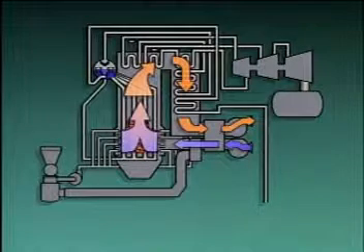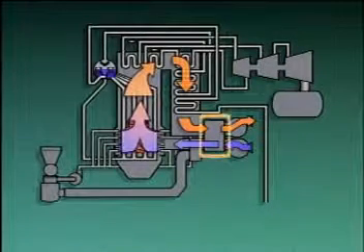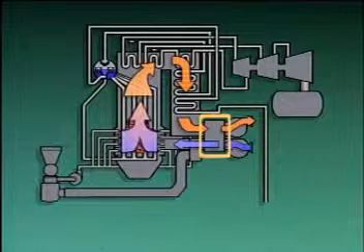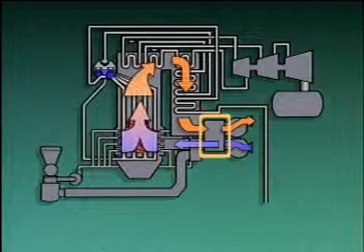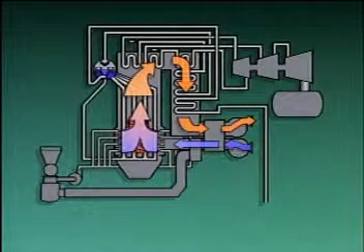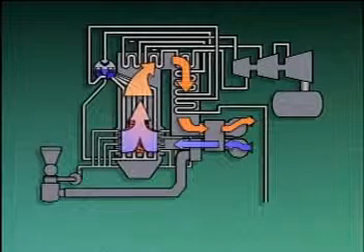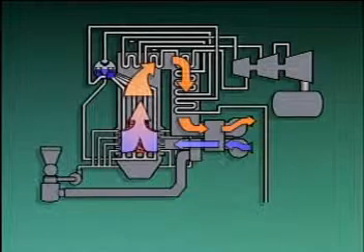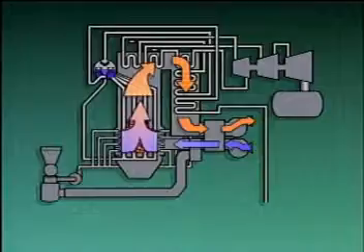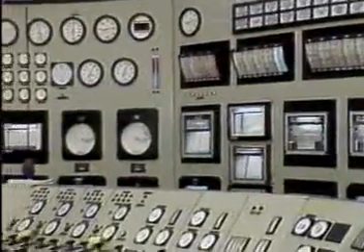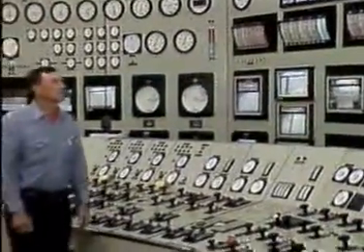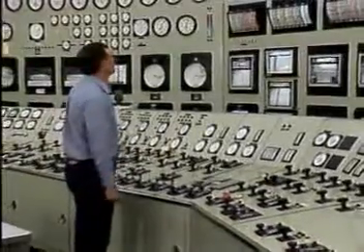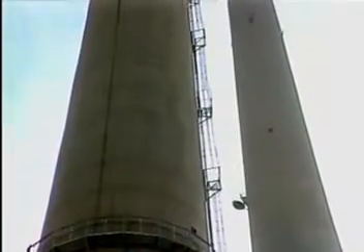For example, sulfuric acid, which is very corrosive, can form on the air preheater when sulfur trioxide in the combustion gases combines with water. To prevent the acid from forming in the gas flow path, combustion gas temperatures are kept above the dew point. The dew point is the temperature at which water vapor in the gas flow path will condense into a liquid. If the water vapor does not condense, the danger of corrosion to the air preheater is greatly reduced. Eventually, combustion gases are released into the environment.